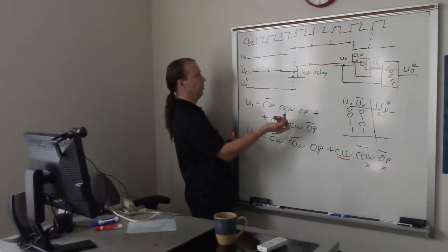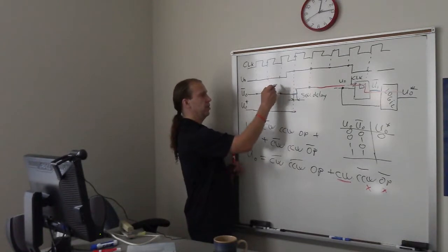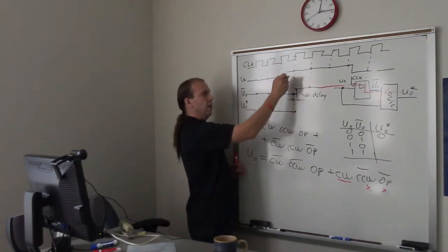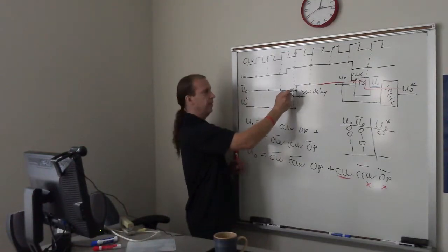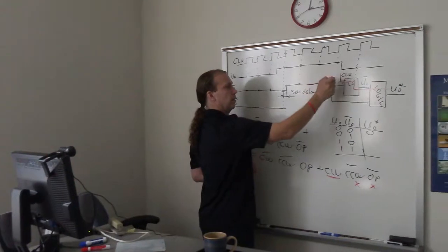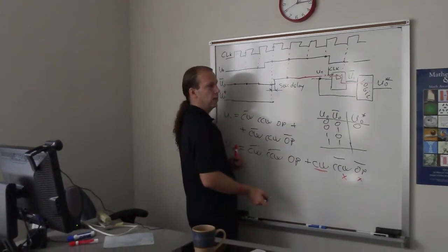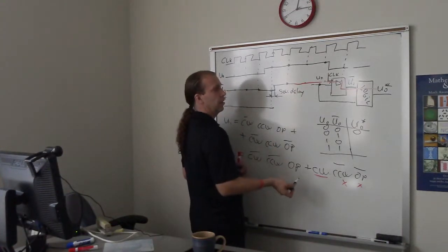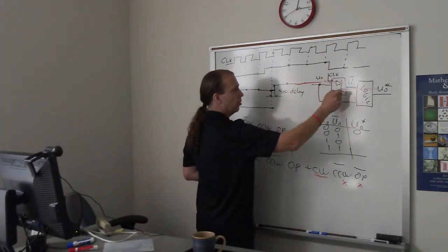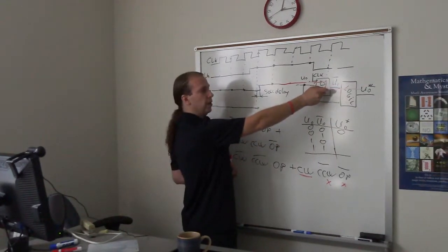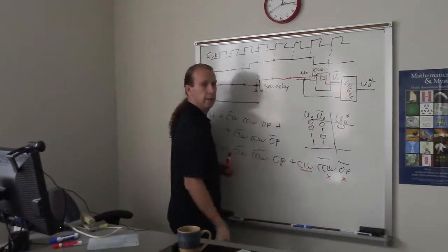Look what is happening. Combination 0, 0. For only one clock cycle, combination will be 1, 0. Then for many clock cycles, combination will be 1, 1. And then when we release the signal, combination will be 0, 1, also for one clock cycle. And then 0, 0 again.